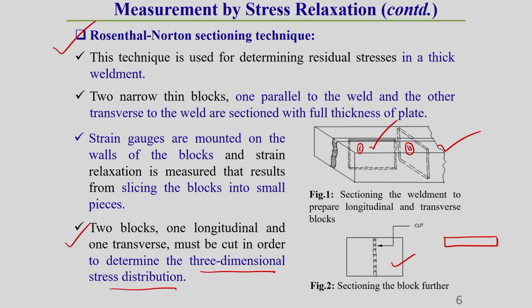Let's take a specimen which is in tension, let's say the initial length was this much. Due to locked in elastic strain, it is elongated like this, the final length LF, and the initial length was, let's say, L0. Now once we release this strain, that means once we remove the support from here, it will return back to its original shape, correct.